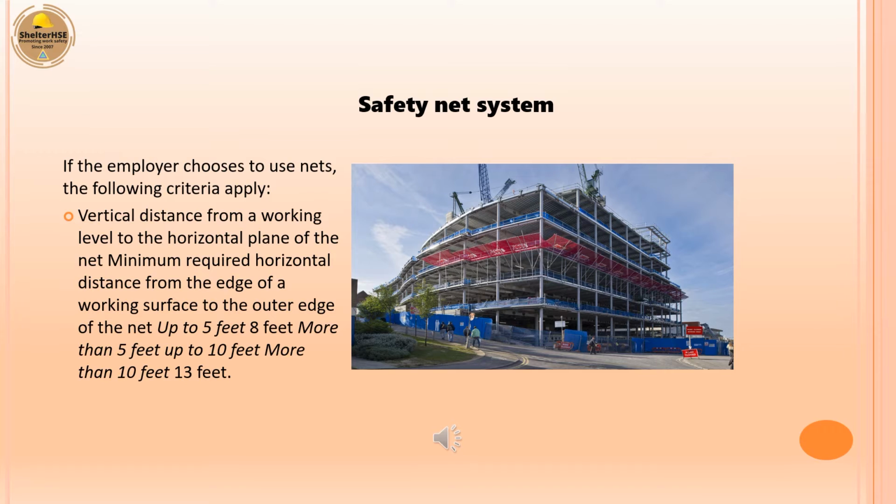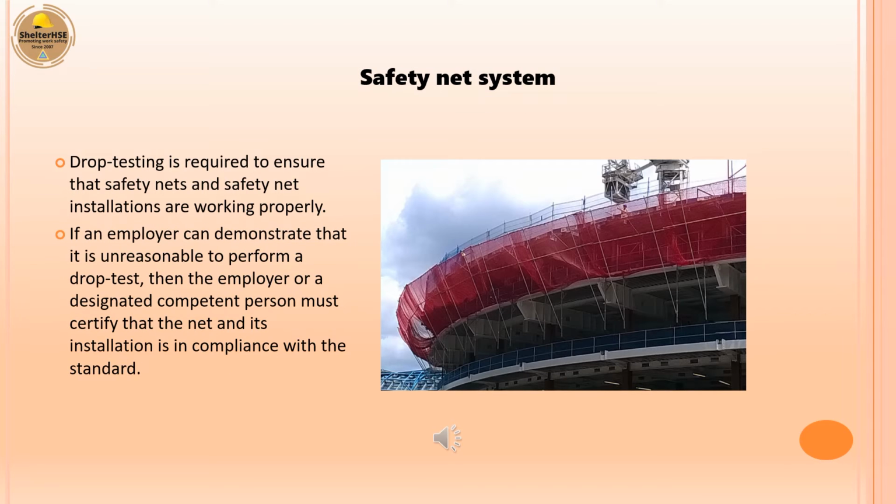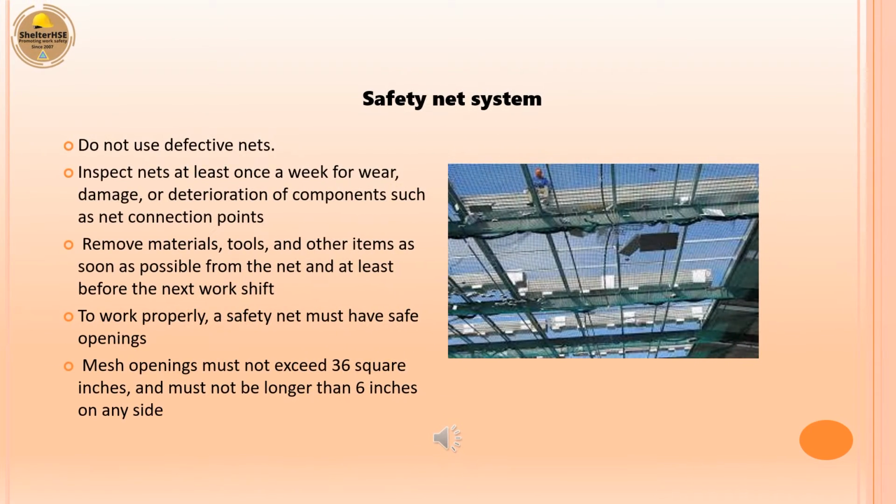Drop testing is required to ensure that safety nets and safety net installations are working properly. If an employer can demonstrate that it is unreasonable to perform a drop test, then the employer or a designated competent person must certify that the net and its installation is in compliance with the standard. Do not use defective nets.